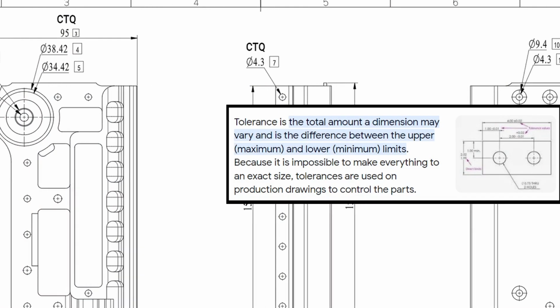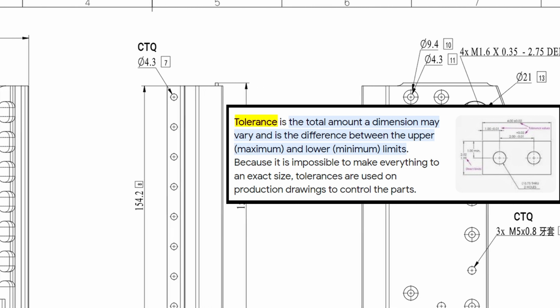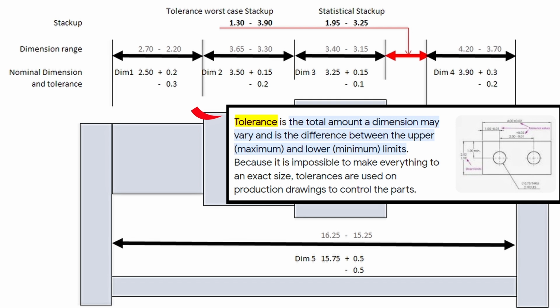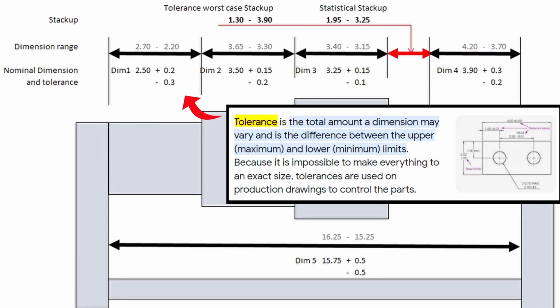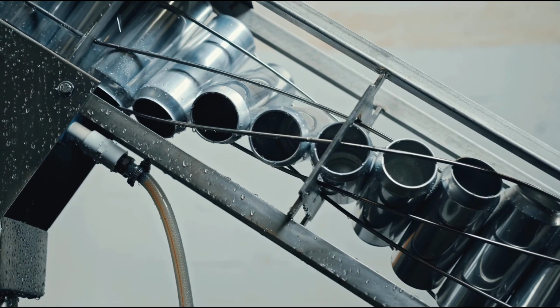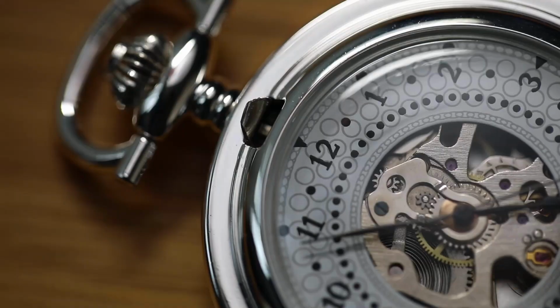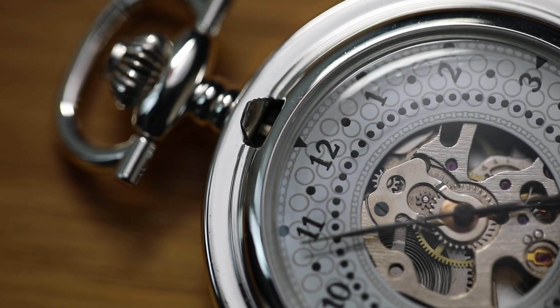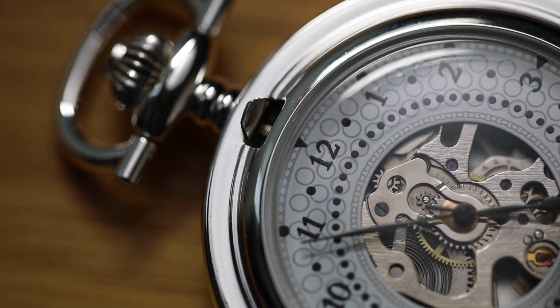Where does the term tolerance fit in? Tolerance describes the degree to which a measured value deviates from the ideal, usually expressed as a plus or minus variance. In our physical world, all objects, man-made or natural, have some degree of variation from one thing to another, even if they appear to be exactly the same. It's inevitable and it's okay. Some amount of tolerance is necessary if you want a mechanical device to be able to move. If it's too perfect, then it would be inert.